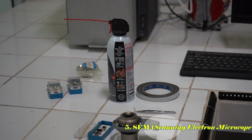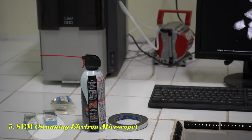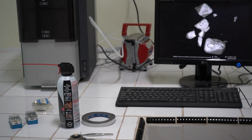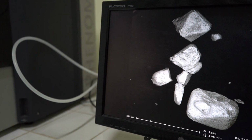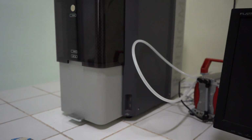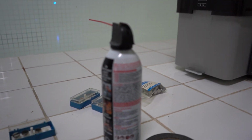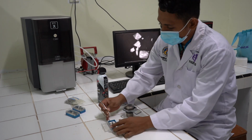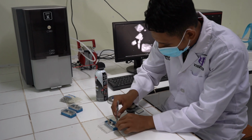The last one is SEM. A scanning electron microscope, or SEM, is a type of electron microscope that produces images of a sample by scanning the surface with a focused beam of electrons. The electrons interact with atoms in the sample, producing various signals that contain information about the surface topography and composition of the sample. The electron beam is scanned in a raster scan pattern, and the position of the beam is combined with the intensity of the detected signal to produce an image.